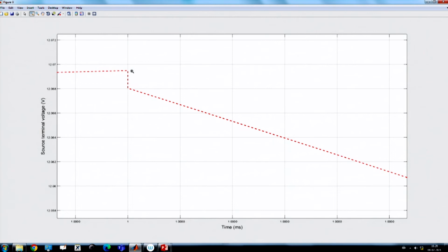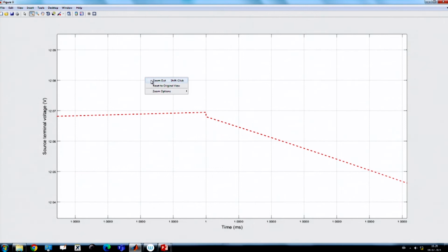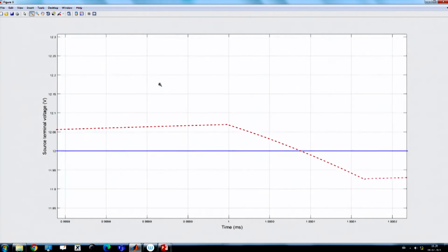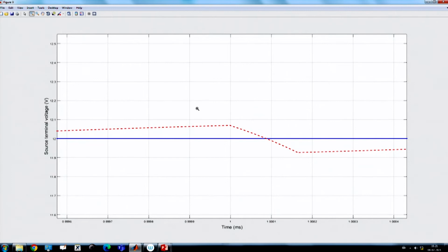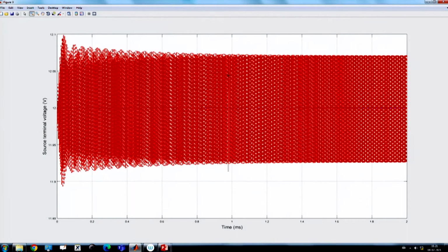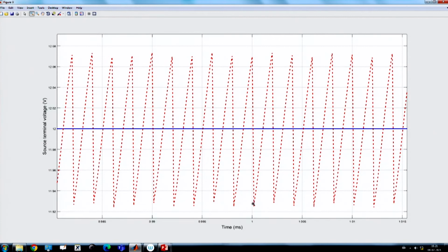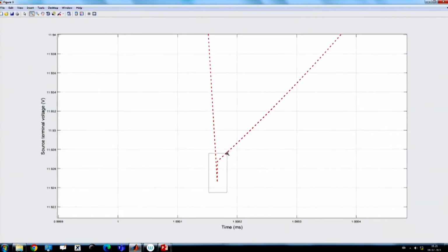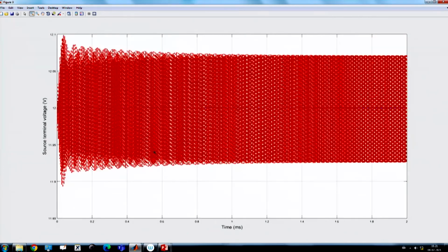because of ESR of the source RC circuit, and then again if we go here, okay, again if we take up this, so here also you will get one jump. Okay. So, this jump phenomenon is because of the ESR; it will be a direct jump when you suddenly apply a load step and when you suddenly remove it. So, here we are not applying any load step, because the buck converter current is discontinuous, and that appears like a load step to the source, and that is why it is responding.